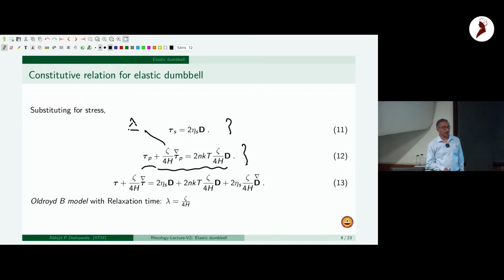And so if you have a rod-like system, then there is no elasticity in the system, right? Because this is a dilute rod system. So there is going to be a modification to viscosity, but no elasticity in the system. And when you combine both of these, you get what's called an Oldroyd-B model, where there are additional terms which are associated with the solvent viscosity. Then this is the polymer contribution, which you could call eta P. And then there is an additional time constant, which is associated with the solvent and polymer relative contributions.